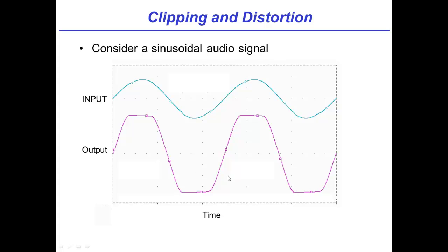I see. So just to be succinct, even if you don't know this at home, any repeating or regular waveform with time can be represented as a sum of many different sinusoids. That's right. So if it's a pure sinusoid like the input, that's obviously just one sinusoid. But this thing in the bottom that's more complicated, it is regular, however, it repeats. So we can have some sum of sinusoids, who knows how many, to get a good representation, but that's what you're saying. Okay, right, so far so good.